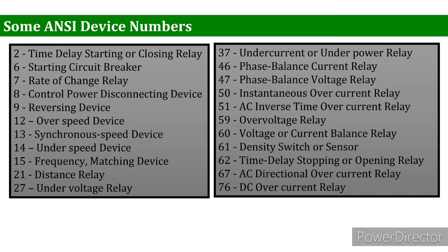Along with that, as I mentioned earlier, in single line diagrams the name of the relay in most cases is not mentioned. Only the relay number is mentioned. So the engineer has to identify the relay on the basis of the number. So these device numbers are also important. Along with that, if you procure any device, these are the standards.